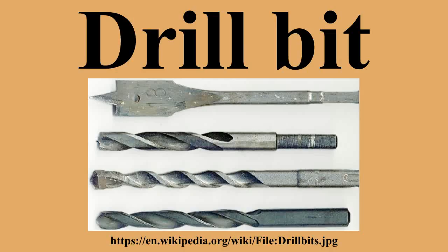Trepan, sometimes called a BTA drill bit, is a drill bit that cuts an annulus and leaves a center core. Trepans usually have multiple carbide inserts and rely on water to cool the cutting tips and to flush chips out of the hole. Trepans are often used to cut large diameters and deep holes. Typical bit diameters are 6 to 14 inches and hole depth from 12 inches up to 71 feet.